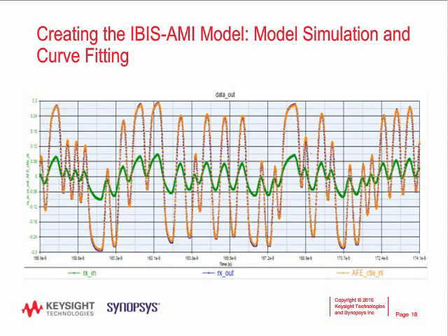Again, this is similar, an illustration of the receiver model containing the CTLE, the CDR. This is an example of a plot for the fitted response of the RX-AMI model. The model simulation output, the AFE, CTLE, NL, in orange there, is compared to the circuit simulation output of the RX out, which is blue. So the same RX input, and again, the RX input is the H-SPICE simulations that we're trying to match the response of our model to, and again, the fidelity of this matching is a function of the curve fitting and the algorithms used to curve fit and how extensive your simulations are run.